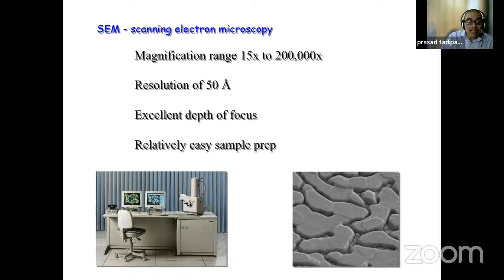And by varying the electrical signal to this pair of coils as a function of time, the electron beam is moved in a straight line across the sample and then returned to its original position. Similarly, the process is repeated with the other pair of coils.